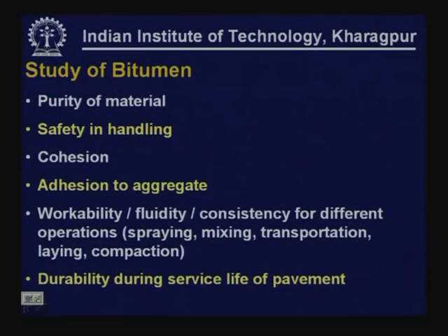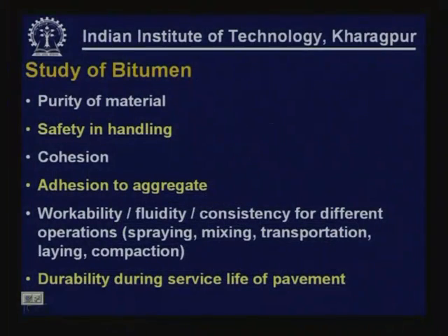Next thing is the aspect that is related to safety in handling the bitumen, because bitumen is going to be heated, and when heated, whether it is safe to use, at what temperature it is safe to use, we have to understand that. We have to have some idea about the cohesive properties of bitumen, also understand the adhesive capability of bitumen to aggregates that we are going to use in a particular project.